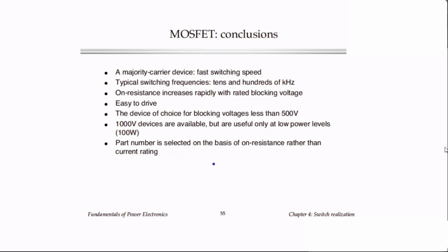One other thing, these devices generally are loss limited. When we design a power converter, we generally don't select the MOSFET based on the current rating, which is a peak current rating of the device. Instead, usually we select them on the basis of on resistance and conduction loss. So often we will choose a device with a peak current rating much higher than we intend to use, and instead we choose the MOSFET size to get a given low on resistance as needed in our application. As a result, these are very rugged devices as well that have quite a bit of margin when it comes to current.